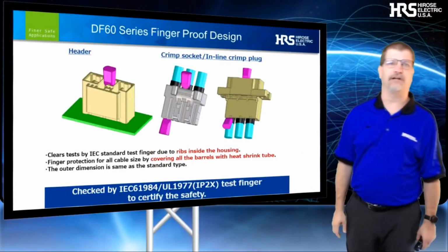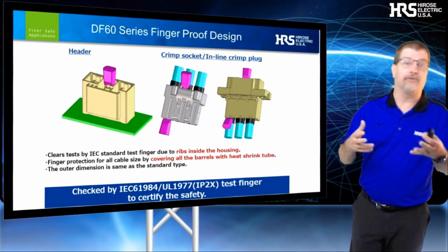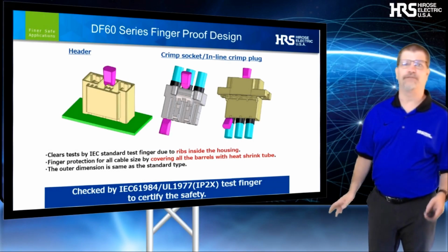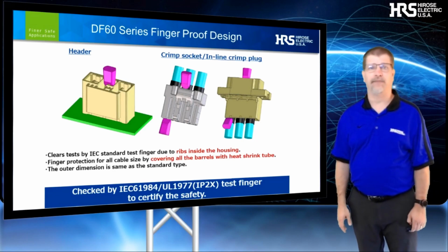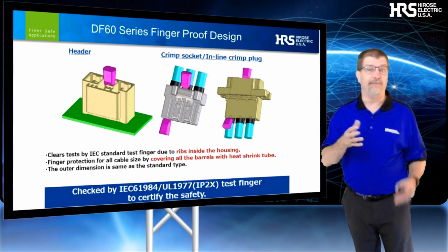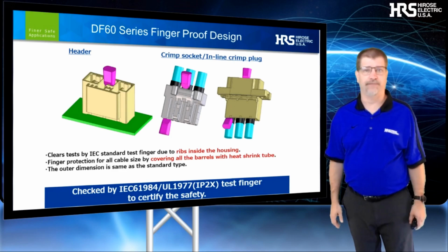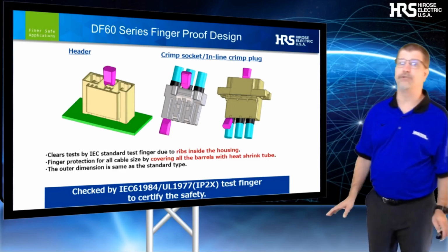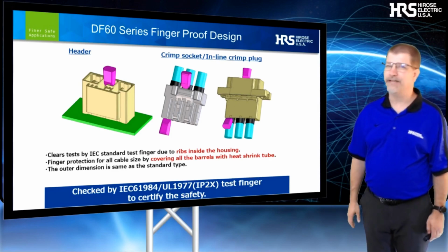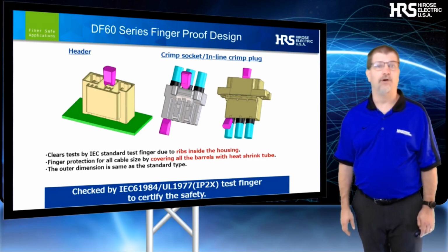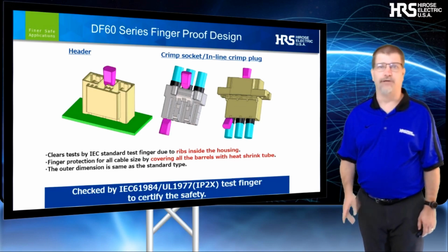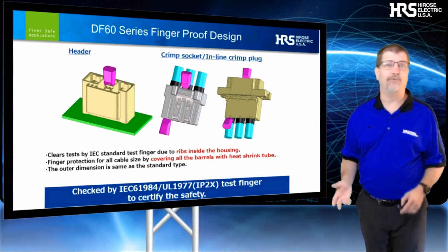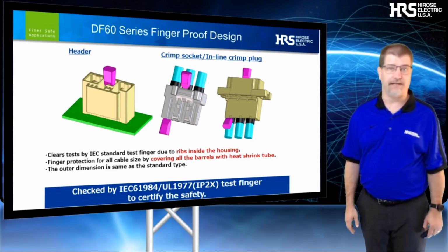Most battery applications are at lower than 48 volts DC. When we get above 50 volts, applications may call for a finger-safe IP20 requirement, when the circuit being used must remain energized during connector usage. What this means is the operator's fingers are protected from accidental exposure to high voltage contacts. The definition typically comes from IEC 61984 or UL 1977, and the requirements are based on a finger probe that will be used for both a mated connection and when the connections are in an unmated state.